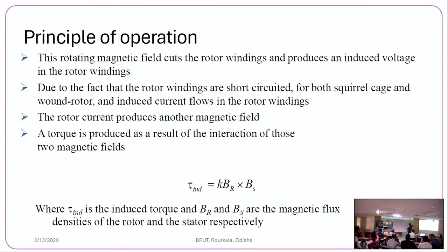And the rotor frequency fr is 50 hertz, the same as the stator supply frequency. I am writing f1 for the stator supply frequency. So the stator supply frequency is equal to the rotor frequency, both are equal, because the rotor is stationary and the relative speed is synchronous speed. That means 50 hertz. The rotor frequency is s times the supply frequency, so with s equal to 1, it equals the supply frequency.